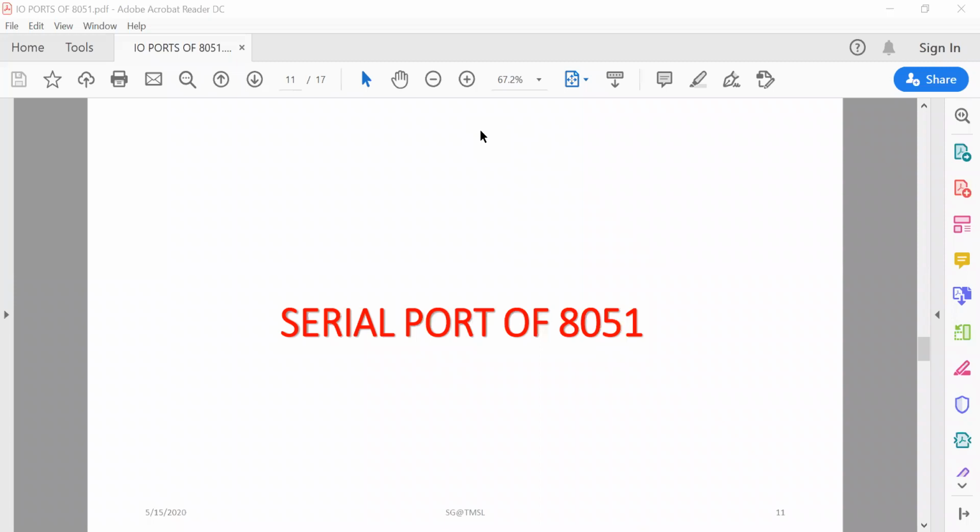A frame is a complete and non-divisible group of bits which can be transmitted at a time. It contains the actual information, that is the data, as well as some extra bits to maintain synchronization and integrity of the data, like the start bit, stop bit and parity bit. These are incorporated into the actual data bits.